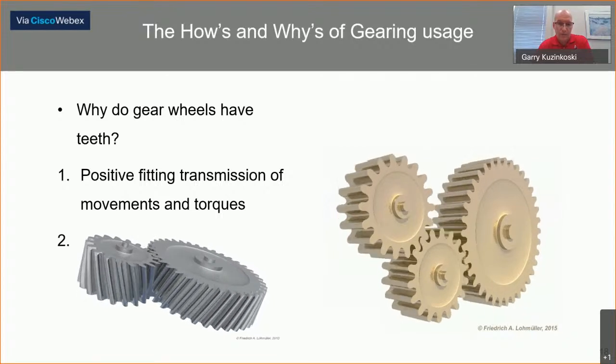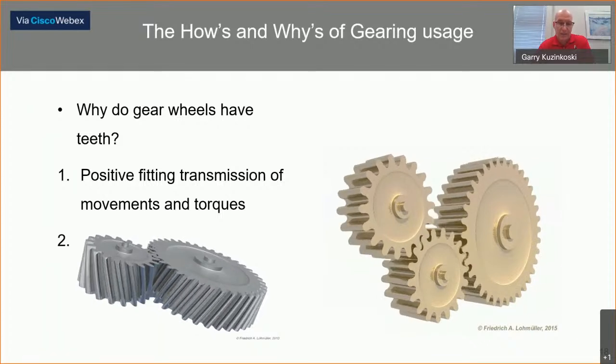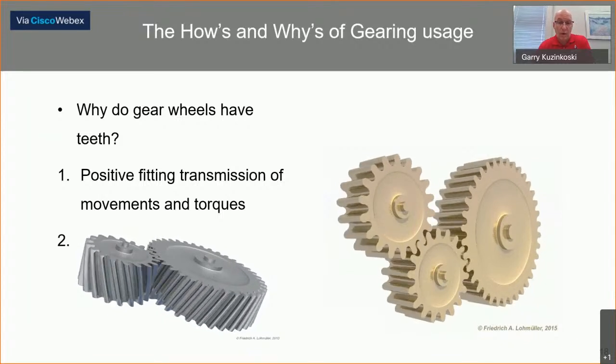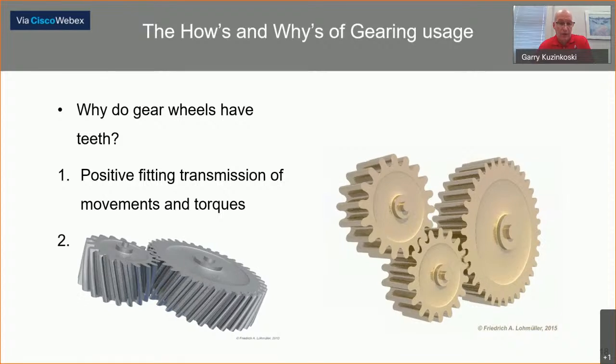So as you can see on the left and on the right, they're fully engaged tooth to tooth, which provides a very, very positive contact. If I were to be utilizing, say, an overhead gantry, and I had simply a wheel moving on a piece of iron, there is a tendency where it could cause a slippage in that, and then I would not be positioned correctly. So gear pretty much prevents that.